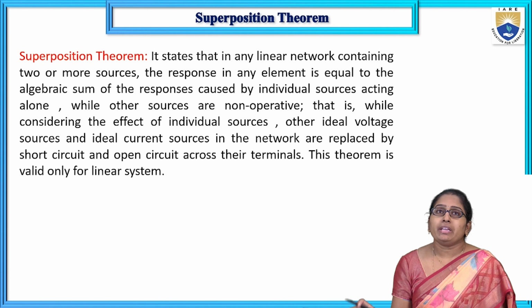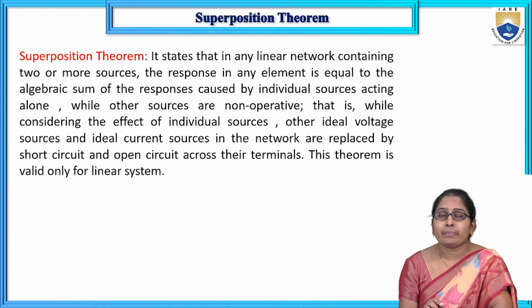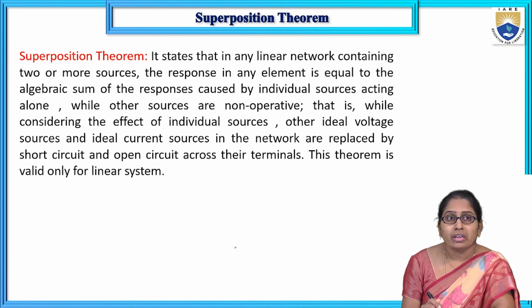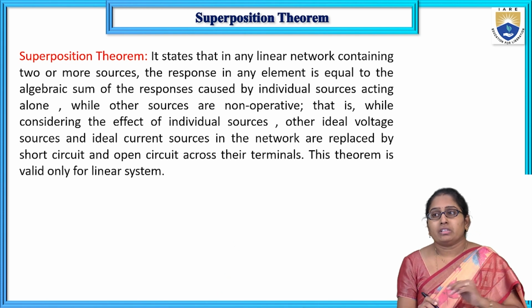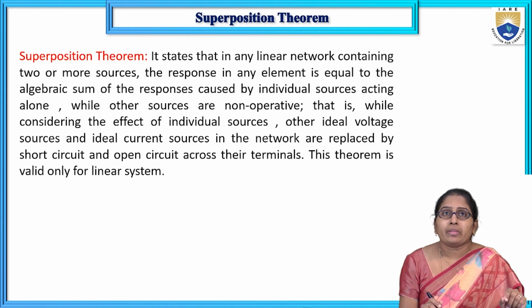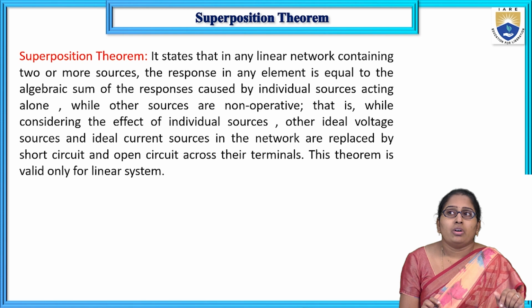Once again, I am repeating: the superposition theorem states that in any linear network containing two or more sources, that is a basic point, the response in any element is equal to the algebraic sum of responses caused by individual sources acting alone, while other sources are non-operative.